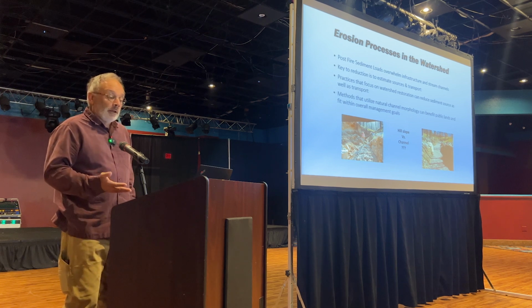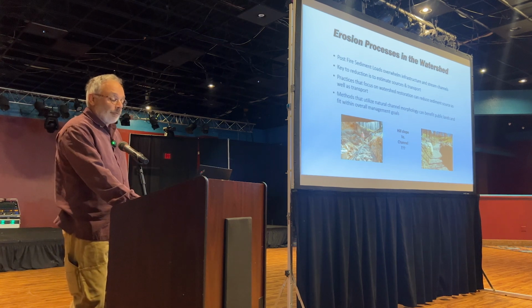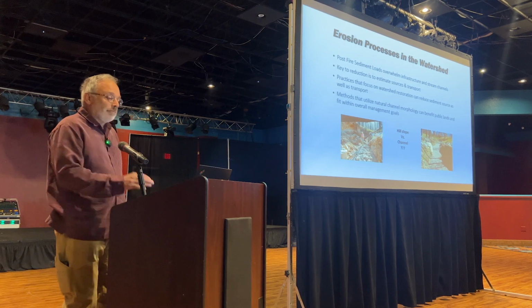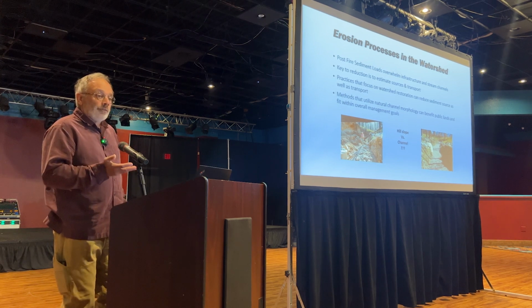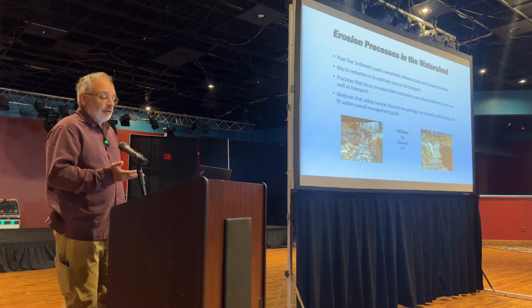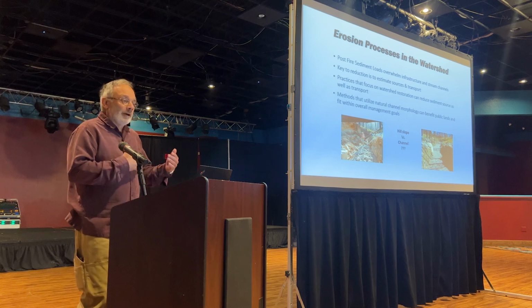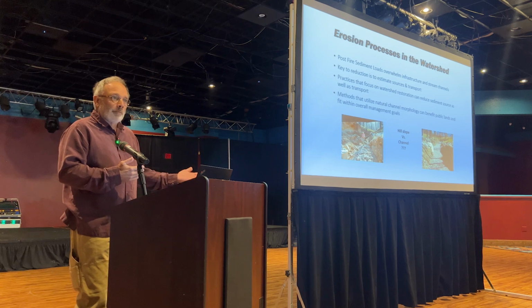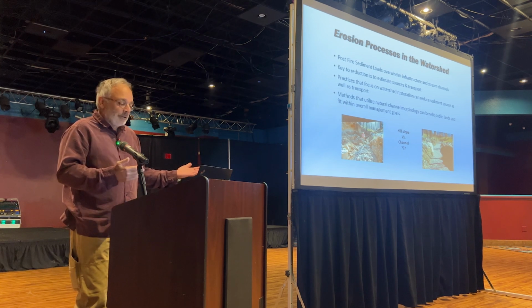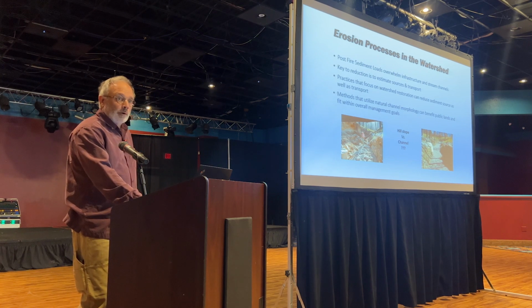and all of the cool methods that people have been talking about so far, and get you back to a properly functioning watershed. One of the key aspects of this is understanding where the sediment is coming from. Is it hill slope processes, or is it a channel process? Because if you are actively trying to fix something or enhance something, you need to know what process you're working on. Hill slope and channel are two big important resources, and they take different methods to work on.